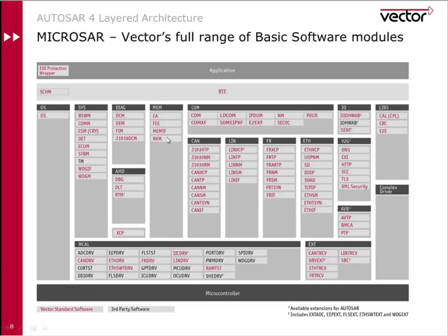Next along is the memory stack, and in here we have EEPROM abstraction, flash EEPROM emulation, memory interface, and NVM, the non-volatile memory. So of course there's often a high dependency on the diagnostic modules, on also the memory interface as well, because when diagnostic events occur, those have to be logged into memory. And so the specifications are written in such a way that there's often a dependency between two parts of the stack. The diagnostic modules place calls upon the memory modules, and those memory modules have to work in an AUTOSAR way and are expecting AUTOSAR type calls from the diagnostic modules.